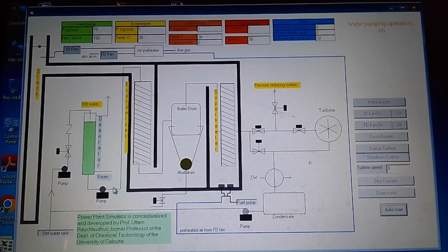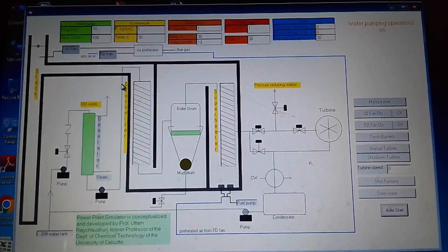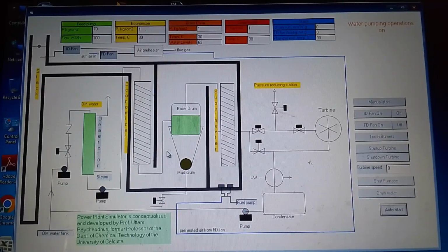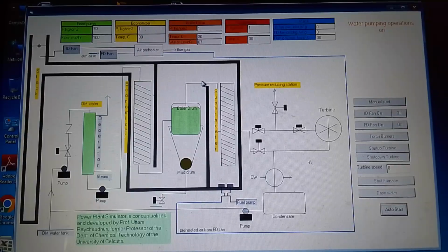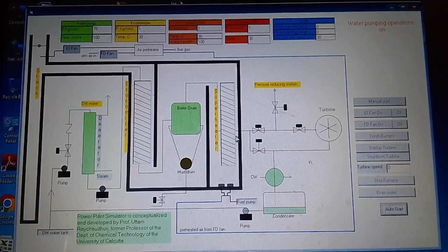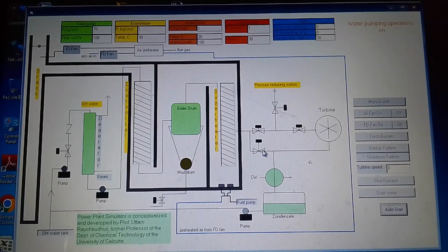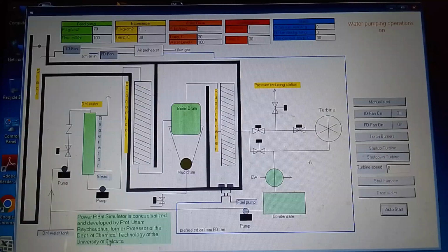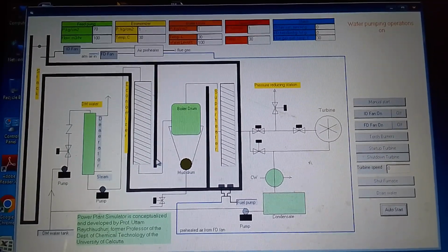The deaerated water is pumped by a high pressure pump through the economizer tube bundles, and then this water goes to the boiler, and finally fills the superheater, and from the superheater bundle it goes back to the water cooler, and then to a steam recovery section where the steam condensate is collected and returned back to the pump. Initially this water circulation is started for testing the leakage as well as for stability.